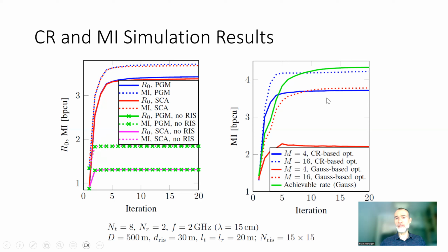So in other words, for the constrained constellation, like QPSK, it is highly important to get the gains by using not the Gaussian approximation, but this particular cutoff rate optimization.